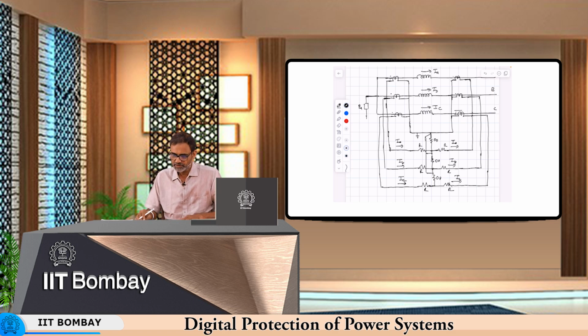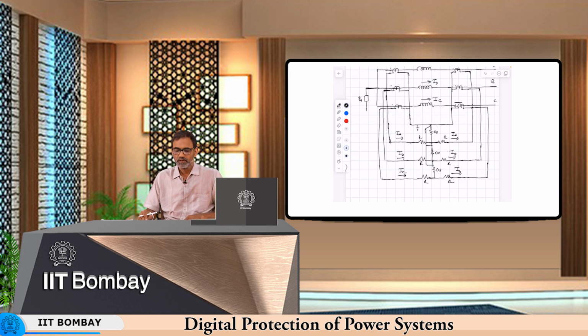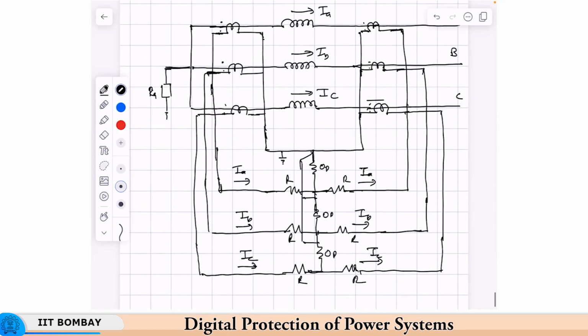Okay, so this completes the differential relay circuit. Now, while setting it, it is similar to a percentage bias differential characteristic like we have seen, but the slope could be lower, as you do not have problems of magnetizing inrush and no load current and all that in the case of generators, unlike that of transformers.